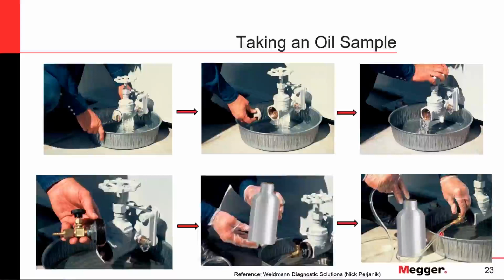Okay? So after you finish filling up your last container, and you have all of them sealed, proceed to remove the tubing. Of course, close both of the valves in your adapter from the sampling valve. Then proceed to remove the adapter and make sure you leave everything clean. Again, this will facilitate future samplings.